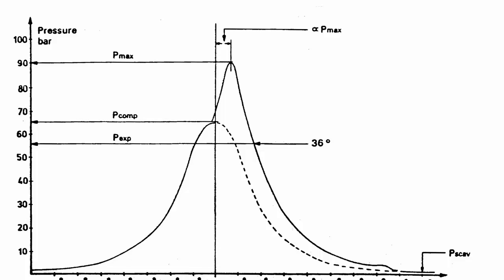Heavy residual fuels, depending on the fuel quality, that can vary drastically, and that will change the timing of the engine. So for heavy fuel oil engines, it's very important that you can change the timing of injection depending upon the ignition quality and the ignition delay of the fuel that you're burning.